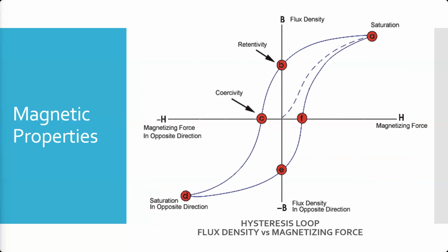Okay, so that's the point where we're probably going to hope to meet, somewhere just before here, right? Just before we reach that max voltage. So now when we get back to where the voltage is effectively 0, which is a small fraction of a second, in an AC system, we can say our force is off for a 60th of a second here. We're still going to have magnetism. This is exhibiting retentivity. Most of those individual poles in the part are aligned, but not quite all of them. A few of them have started to scramble because they're not being forced into that position of alignment anymore.